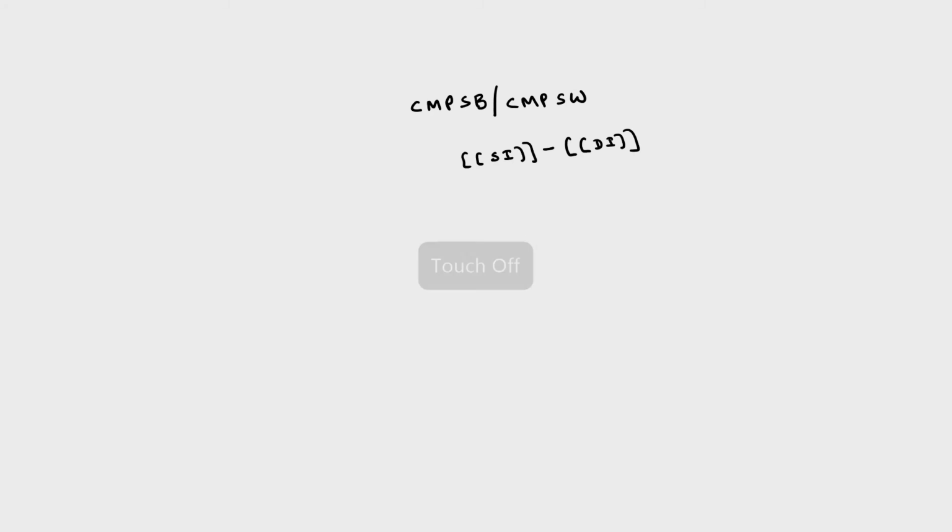Now, again you do not have to perform this repeatedly, so you have to use the same thing. Suppose I write MOV SI, 5000H, MOV DI, 6000H. I want to compare 100 decimal data. So, I take CX with the hexadecimal equivalent of 100, which is 0064H. Then I want to compare from 5000 to 5063 bytes.